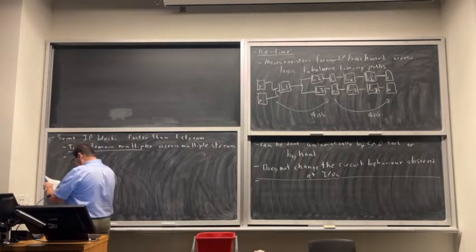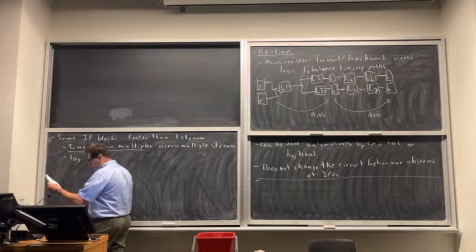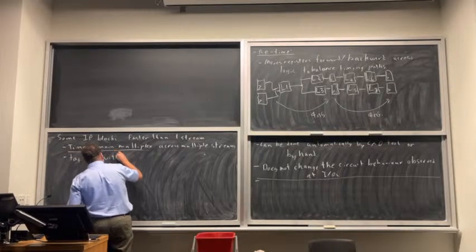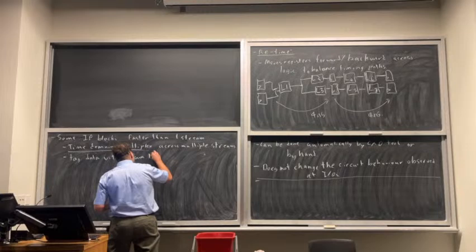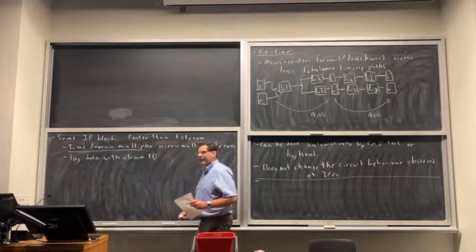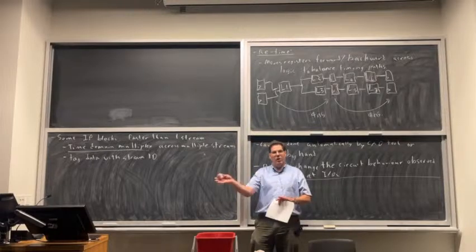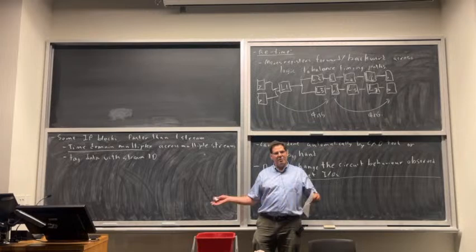You can add one more thing in this case, which is you can tag your data with the stream ID. If I do that, I could send multiple streams of data into this IP block, and its output's going to be all interleaved, but I can look at the stream IDs to take it apart again.